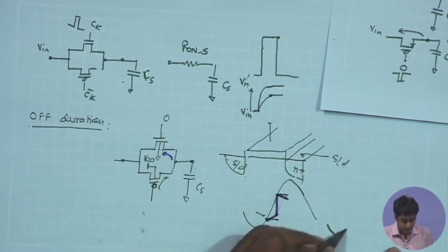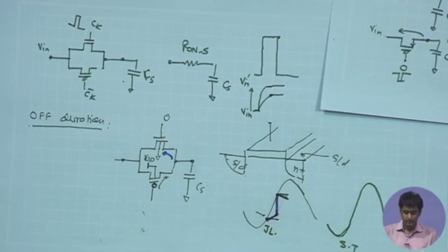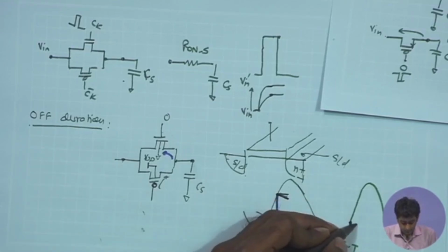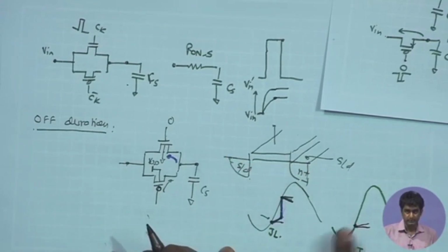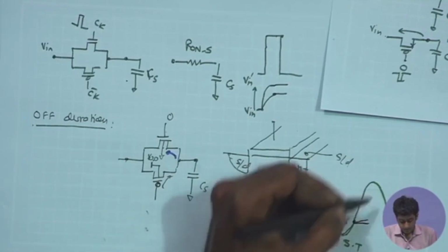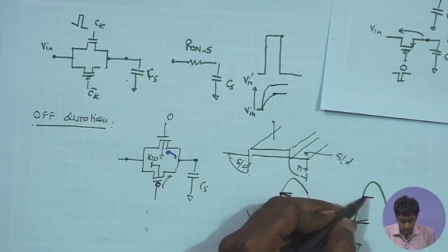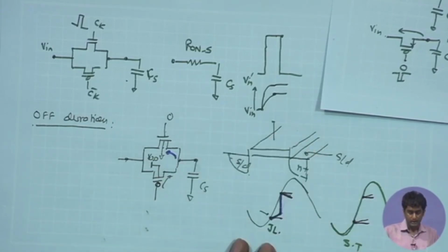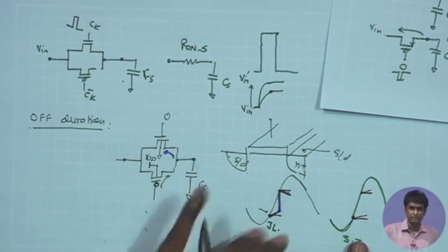If I take another example where the subthreshold leakage becomes more dominant, and this is the sampled value at a particular instance and we want this to remain constant, rather than remaining constant, it will increase a little bit because the input signal is increasing. And likewise, if I am sampling the data over here, here also we will have the same polarity because the input signal at the next sample is increasing, therefore it will slightly increase, and if I am going towards the down going slope, it will have the opposite effect. So, this is the case for subthreshold conduction, when the subthreshold conduction becomes dominant.